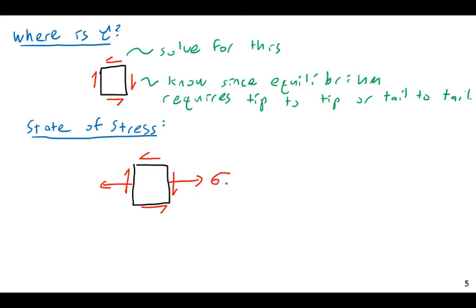What that means is, say we're loading it only with vertical loading. If you're putting loading along the top of the beam, you'd have bending along only one axis. If I apply a horizontal loading to a beam, then I would have moment in the other direction as well. So this sigma is going to be M y over I, and this tau is going to be equal to VQ over It. So let me work through an example of calculating this.